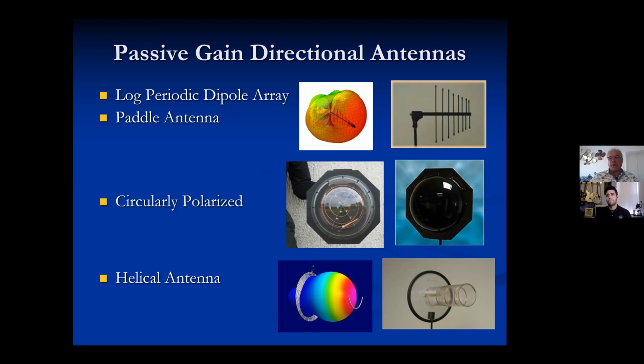Sure. So a fractal antenna doesn't have a ton of gain. I have played around with fractals. We're talking now not on a human body, obviously, but backstage up on a panel somewhere. I think Clair started using them a bunch of years ago, and I did a lot of testing. And the bottom line is there's no comparison to a helical or a CP antenna. You don't have the gain, you don't have the directivity, you don't have the extent of multi-polarization coverage that you get, and they're also not readily available and they're not cheap. So that's a bunch of reasons why not to use it.